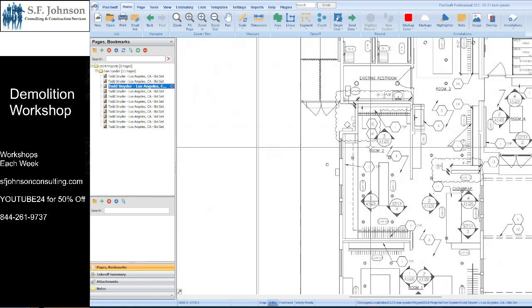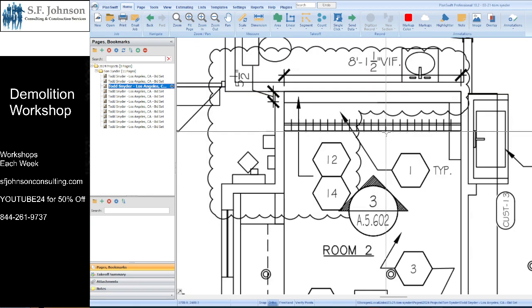And now, is it along the vertical distance of the wall? See, that's very difficult because we could be doing blocking this way down vertically. So one at 10 feet, one at, if we're doing it every 2 feet, one at 8 feet, going this way, or depending on what we're mounting, and there will be some details in the fixture details to tell me, right here actually.